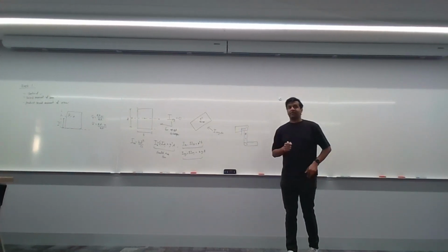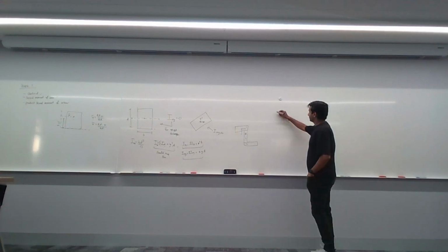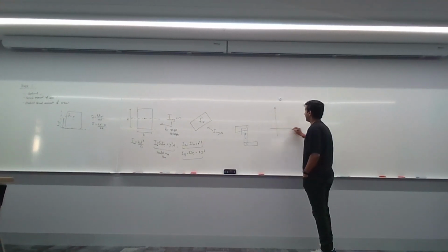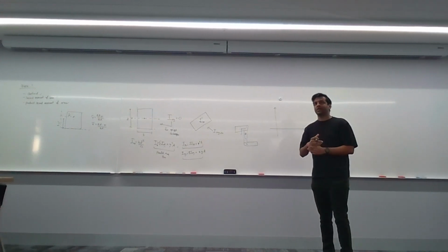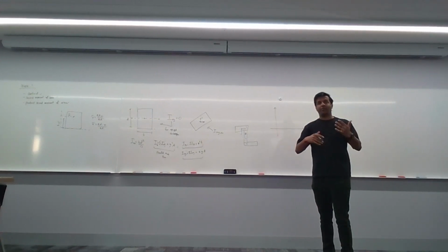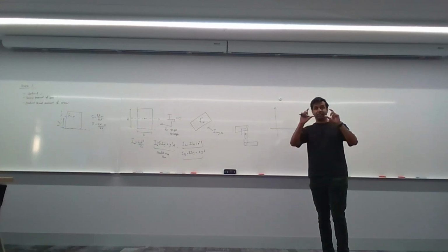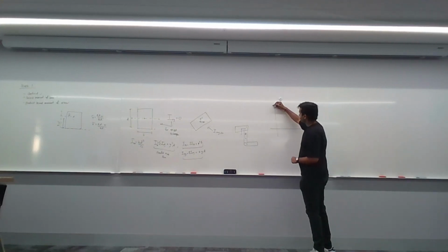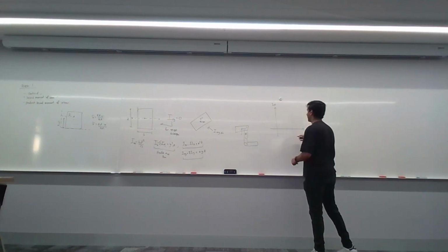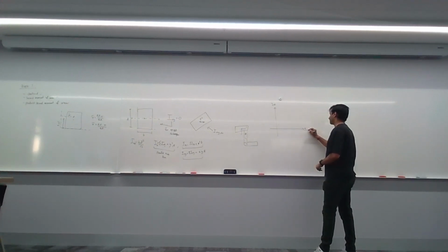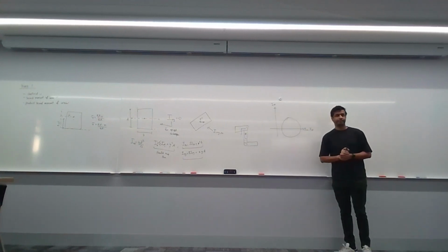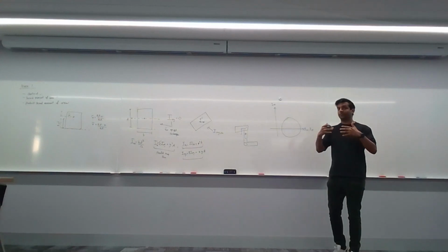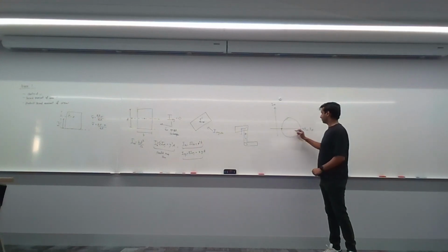Now the last thing that we covered in week 1 is the Mohr circle. Okay, so the Mohr circle is every combination of Ixx, Iyy, and Ixy value for a given shape. So the y-axis is Ixy, and the x-axis is Ixx and Iyy, and let's say that's your Mohr circle, right? Your principal second moments of area are here.